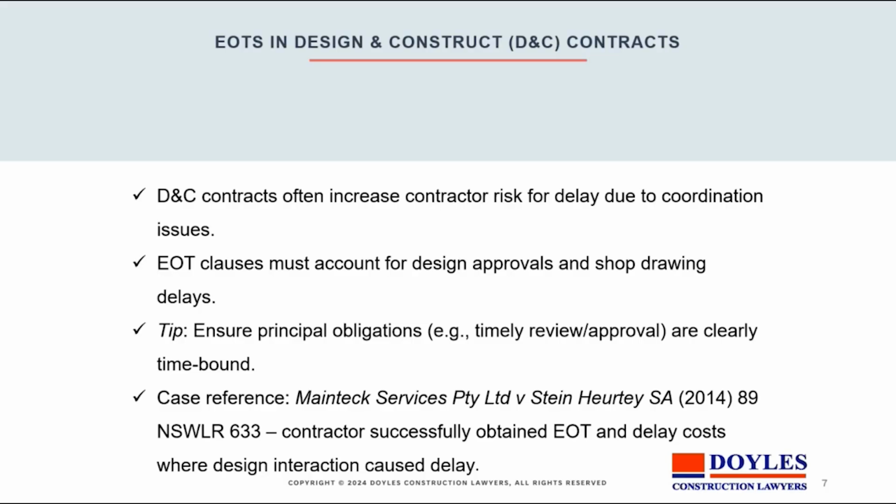The EOT clauses should account for design approvals and also drawing delays. If somebody wants something amended, then that's going to have to go through a cycle of approval, and that often causes substantial delays. The review and approval is best time-bound, in the sense that it's best to have an agreed period where the design approvals or the design adjustments provided by the contractor or the principal's consultants are laid out so everyone knows where they're going.